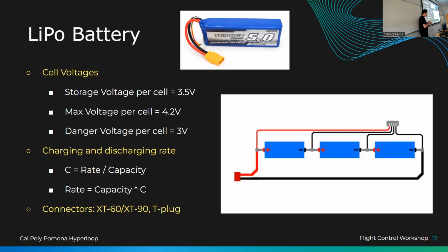The easiest way to explain it is if you stuff yourself with food, and then you go to sleep, you'll eventually feel bloated when you wake up. It's kind of the same thing. If you feed it too much and you leave it alone for like 6 months, and you come back to the LiPo battery, you'll find it has been bloated, and it's out of shape. It's kind of like a human. But again, don't store it at max voltage, don't store it at lower voltage, because either of these will kill the battery. If I feed you too much, or if I starve you, you will die.